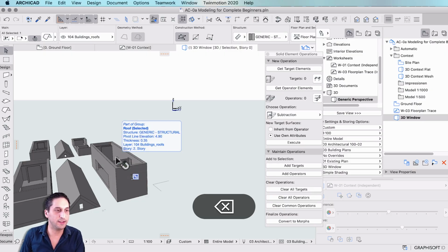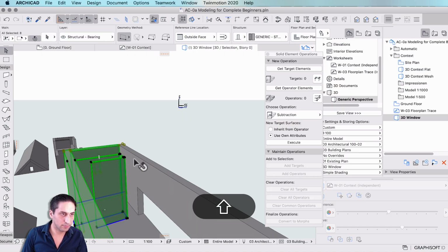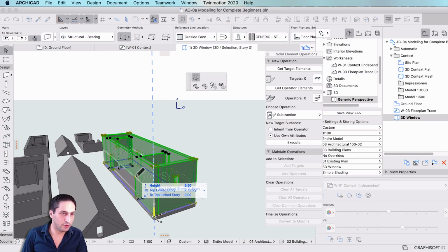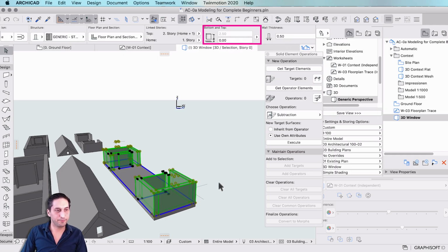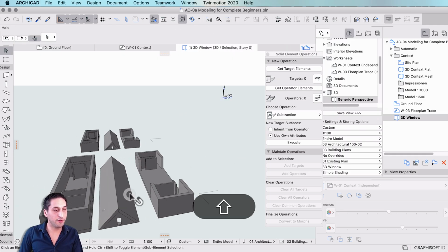All right. Now, for the walls of the first floor, the first thing we need to do is to select the roof and delete it. Then again, we need to reselect all of the walls, and either intuitively lower them to the original height or write down up here in the parameters 2.5. Click OK. You can then, of course, also turn that to morph if you want to.